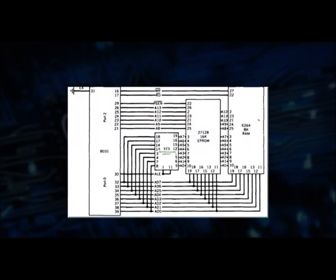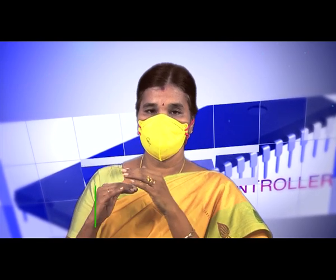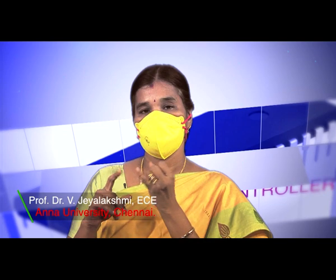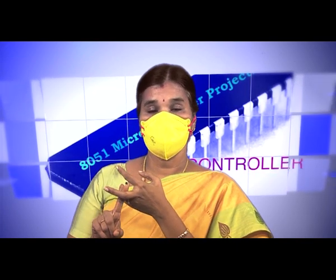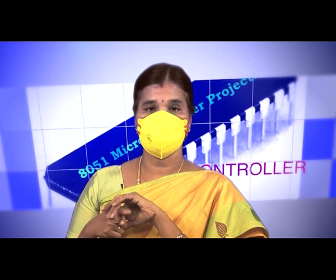This is another example of how the 8051 is interfaced with the memory. Now, I think you have a clear idea how to interface the memory with the 8051: how to interface with the RAM, how to interface with the ROM, and what signals are needed for the memory. For interfacing the memory, you have to know how many address lines are needed based on the capacity, then the data lines, then whether it is read only or read and write, along with the chip select signals.